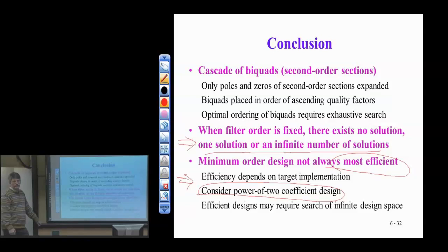You specifically arrange for, maybe, order 2 or 4 or 8. You generally have to double the minimum order to get this one, from what I've experienced. So you have to go much higher order, but the good news is the feedback coefficients in the biquad structure are power of 2, like half, fourth. So they make the math much easier when I multiply. I'm just doing shifts, and I'm not losing precision, which is nice. I'm just shifting things around.